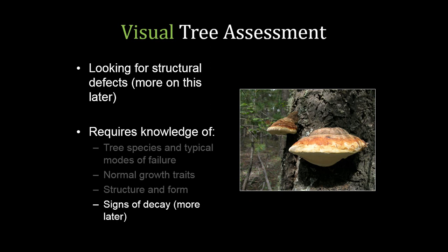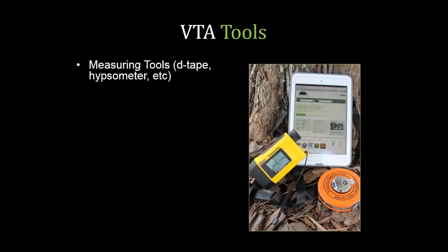And then signs of decay. Signs are positive indicators of decay, that there's definitive proof that there's decay going on, and those things could be things like conchs or cavities, or even some sort of insect shavings from certain species that mostly burrow through decayed wood.